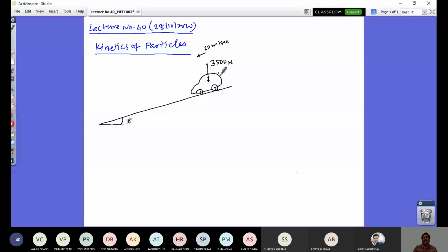That means this complete vehicle is assumed to be a block, right? So the locking is not employed with the modern ABS control system, where it is not locking simultaneously all the time. It will release and lock. That's for safety purposes. But this is an old car that he drives, and he jams on the brake. What is happening? All the wheels of both axles are locked, and then it is as good as sliding of a block on this slope. So you have the surface contact as given by mu k, which is 0.5.